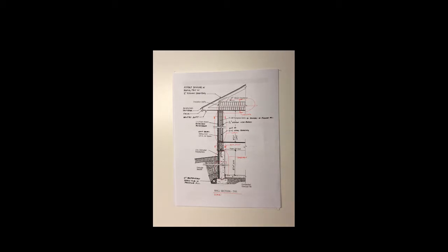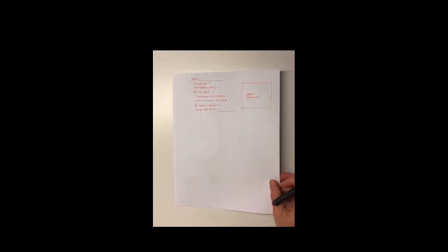And that cavity is going to be filled with whatever type of insulation you decide to use. So in the calculation that I've set up, here would be that larger detail drawing, and for each of those elements, I'm calculating the R value. So I'm going to have that outside air, the wood bevel siding, 3/4 inch airspace, 1-inch extruded polystyrene, and then I'm going to go with the 2x4 with blown cellulose, 1/2-inch gypsum board, and inside air film.